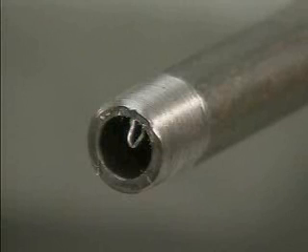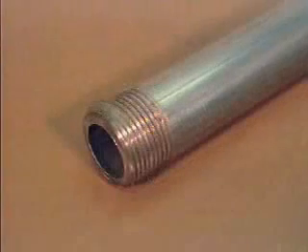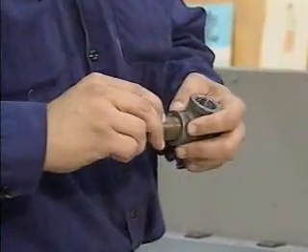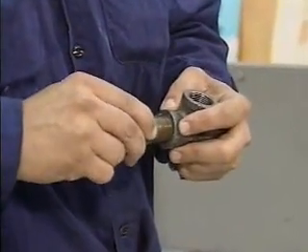No matter which tool is used, cutting pipe can leave burrs and ridges on the inside or outside of the pipe. Burrs are bits of jagged pipe. A ridge is a lip or shoulder that's left on the end of the pipe. Burrs and ridges can restrict the flow of liquid or gas through a pipe. They can also prevent pipes from becoming properly connected to pipe fittings.